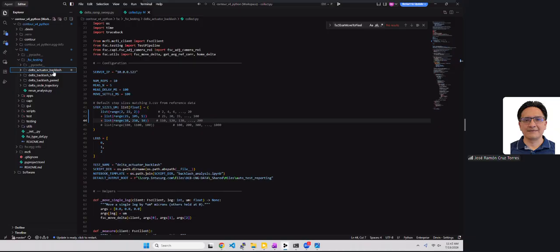I think this is not as bad of a problem, in the sense that the place where hysteresis really shows up is when you have really long moves. The only time we do really long moves is for image-based alignment, which is the starting step where your image starts here and you have to end here, and you use closed-loop control for that. Because that's all in a closed loop, the hysteresis gets corrected automatically.